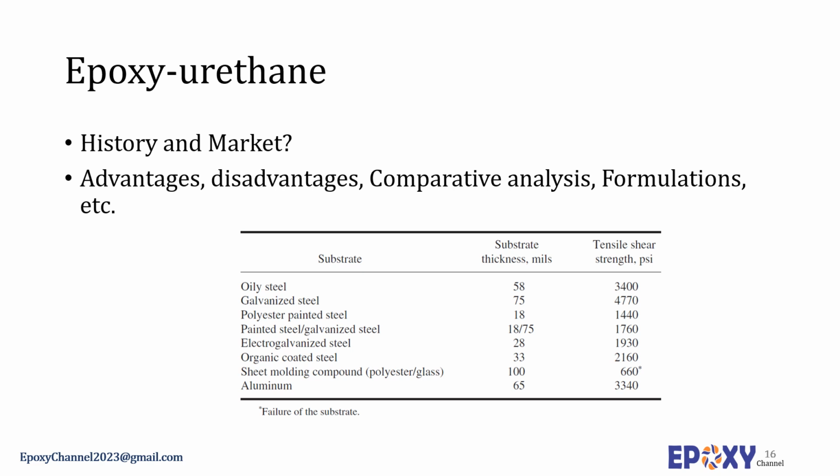Hence, an attempt to cure a mixture of epoxy and isocyanate resins must provide for essentially coupled consumption of all cyanate groups before any of the epoxy rings can react. Another toughened epoxy formulation comes from mixtures of epoxies and urethane oligomers with pendant epoxy groups.